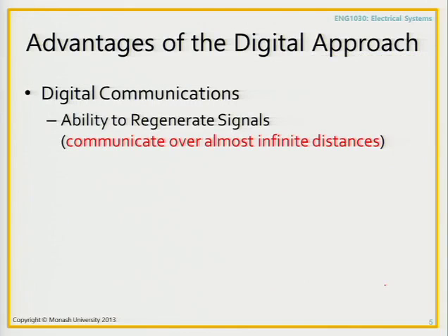Okay. Now, we said that we could use amplifiers, in particular, to amplify a signal to travel long distances. That's great, but when we're using amplifiers, amplifiers introduce noise, okay? And every time you amplify a signal, that noise grows and grows and grows.